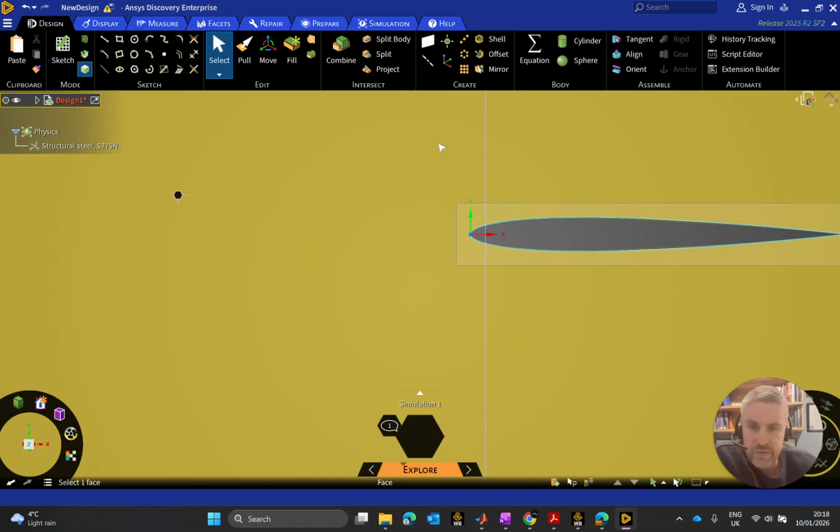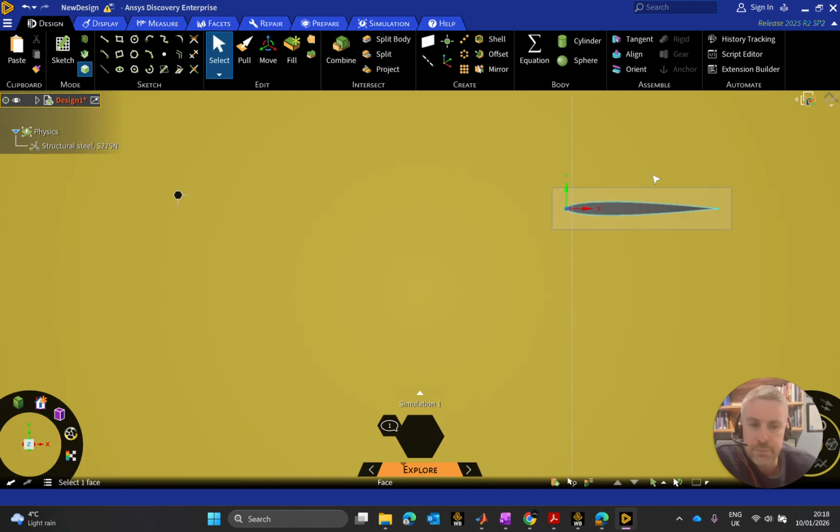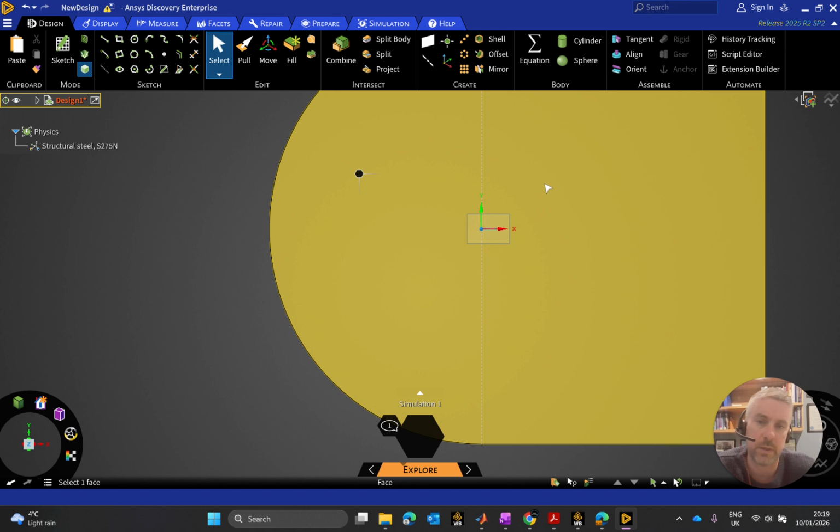Out to kind of a free stream cell size. You can do that, surely, but if you have the computational power available, going with a structured mesh is a much better option. And again, Anthony T and Killian Thomas and others have done this structured mesh, and there's absolutely phenomenal results about it. So there's no point reinventing the wheel.